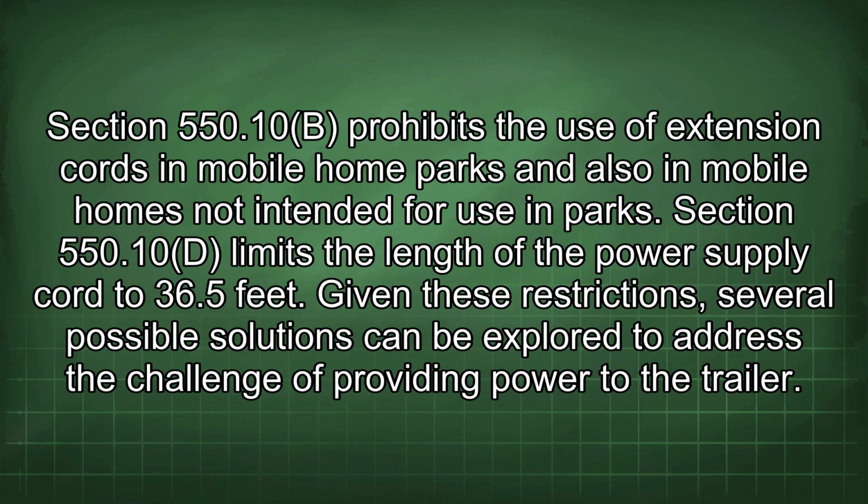Section 550.10(B) prohibits the use of extension cords in mobile home parks and also in mobile homes not intended for use in parks. Section 550.10(D) limits the length of the power supply cord to 36.5 feet.